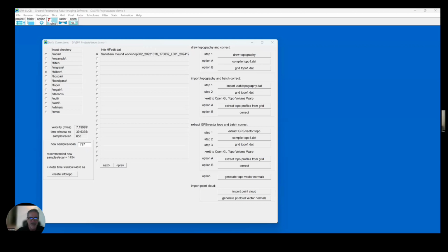They could go in any direction you want. And then if you have mosaic noises, there's different ways to try to correct it. There's a quick way, which doesn't always work so good, but it's called XYZ zero mean grid. What it'll do is compute the mean of each of those blocks and subtract it from the time slices. And you can get rid of those mean amplitudes by that.